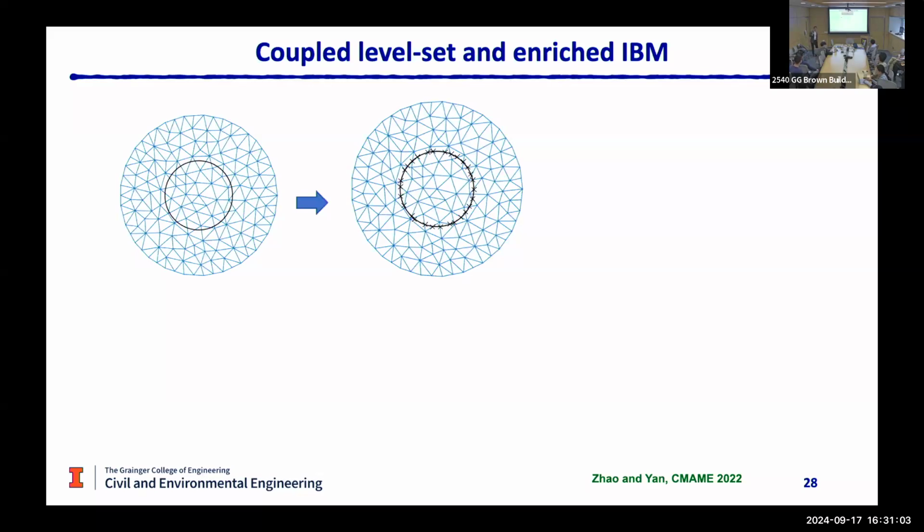However, I still insist on avoiding mesh motion and remeshing because this is too complicated for many people. If you want to keep this feature, you need to resolve all the physical unknowns in the background. However, if you have studied finite elements, you know that for tetrahedral elements, or linear elements, you have a constant gradient inside. If you simulate a thermal process, the temperature gradient is constant within the element interior.